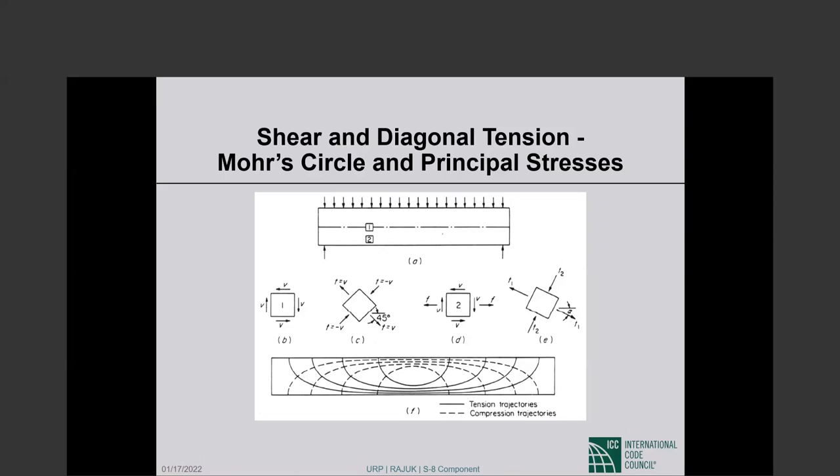Not that we typically do this, but this is very, very important from the shear design point of view, because the central point why I went through so much strength of materials is that, remember, one of the first things I told you is concrete is reasonably strong in compression, but concrete is weak in tension. It cannot carry much tension. And we are seeing significant tensile stresses as indicated by the solid lines.